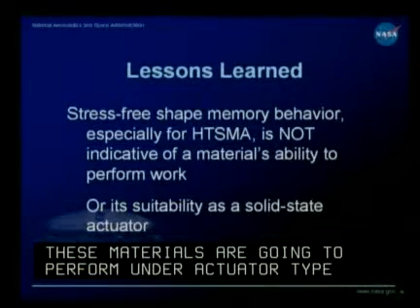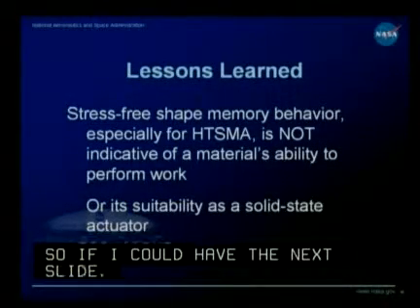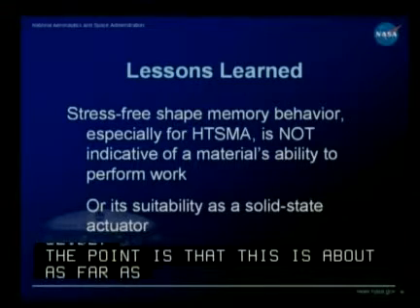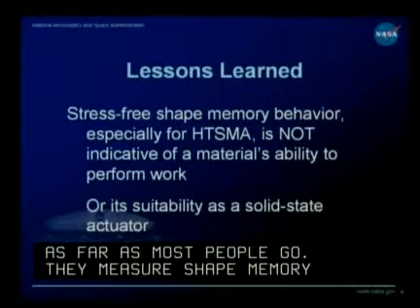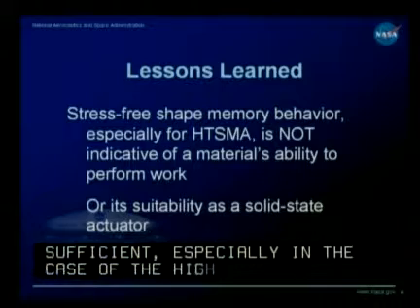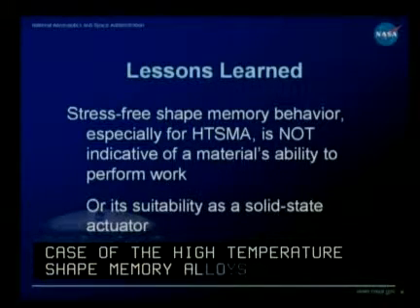The point is that this is about as far as most people go. They measure shape memory behavior, but that's not sufficient, especially in the case of the high temperature shape memory alloys, because it's not indicative of how the material is going to react under stress.